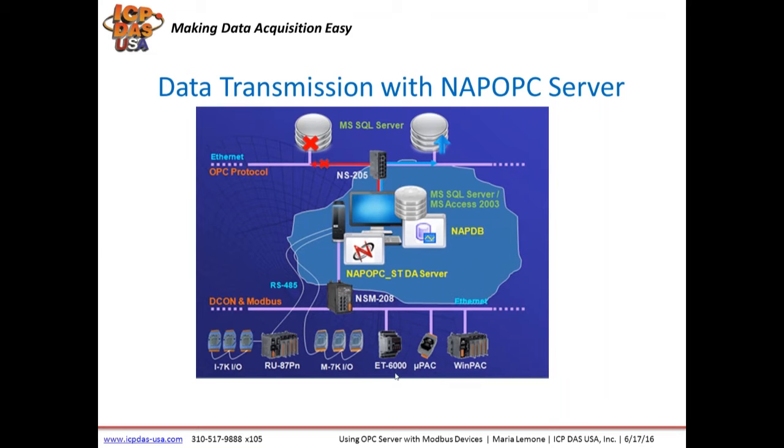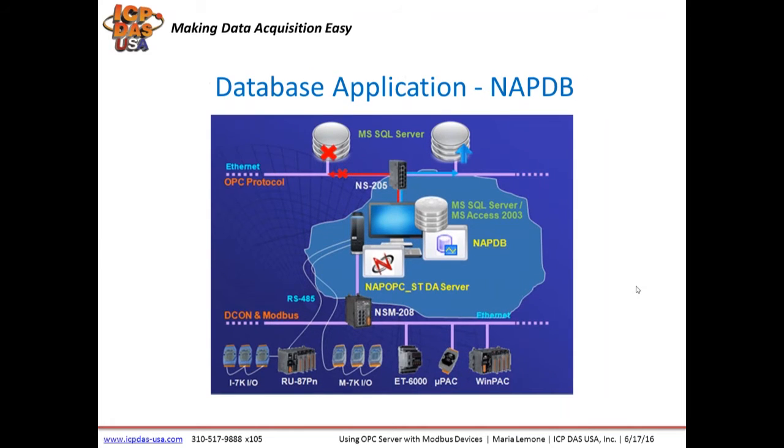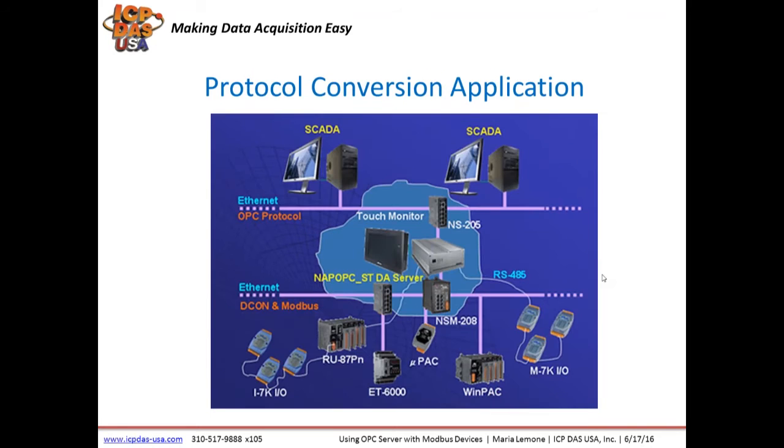You can use Modbus devices and you can network them back to your PC or PAC controllers over Ethernet cabling with Ethernet switches like our NSM208, which has a metal case. You can also use serial cabling over RS485 for Modbus RTU buses.